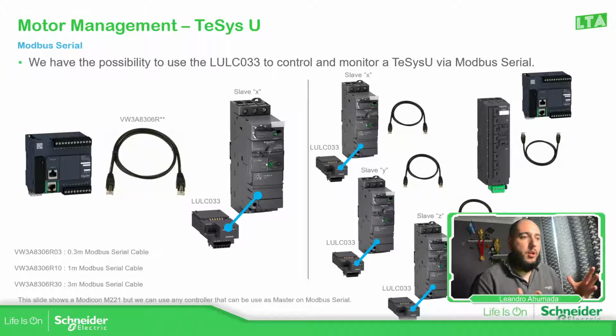As I explained before, in order to connect the TeSys U with the Modicon M221 via Modbus serial, we just need a cable. If you use a Schneider, we can use this one. And of course, on the TeSys U, we just need to use the communication card. Otherwise, no. If we want to use multiple TeSys U, we probably advise to use the Modbus serial hub to connect multiple devices.